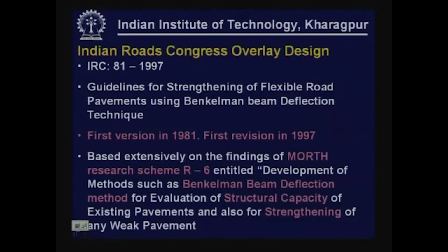This was the main objective of the research scheme. It was to develop Benkelman beam and other similar methods for evaluation of structural capacity of existing pavements. So, a methodology for evaluation of structural capacity of in-service pavements and also for finding out the strengthening requirement of any weak pavements.